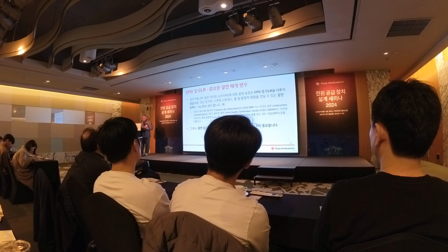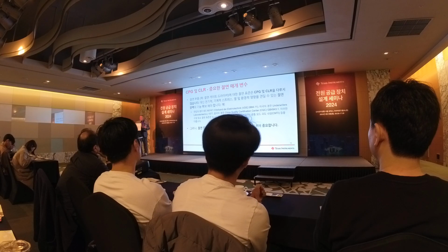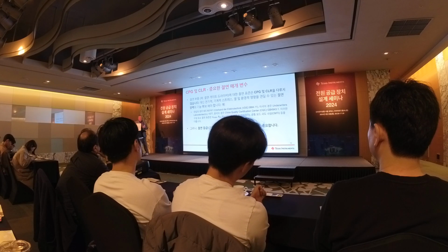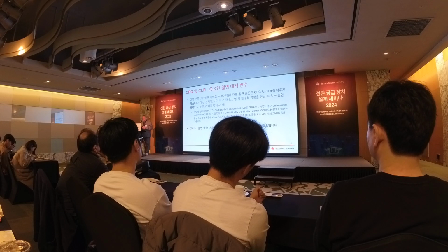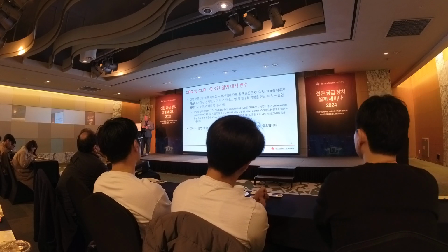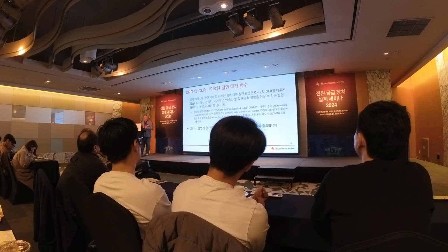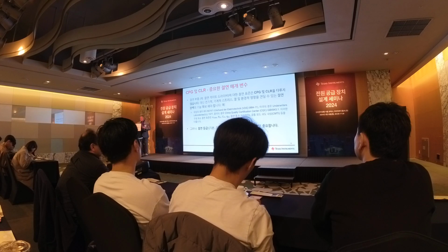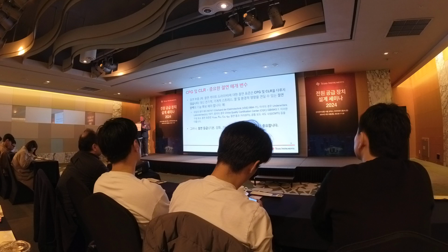So you still need to do other things within your system to make sure that it's safe for the end users. So if I'm looking at insulation grades, the ones that we see most often are basic, reinforced, and functional insulation. Creepage and clearance for those do not matter. That's not what we care about there. For those, we care about user safety. And what we're going to see over the next few slides is what that means for proper functional insulation and for proper use of the circuit.